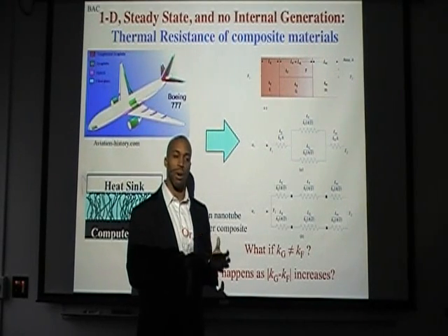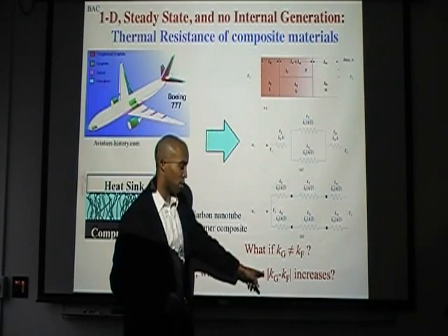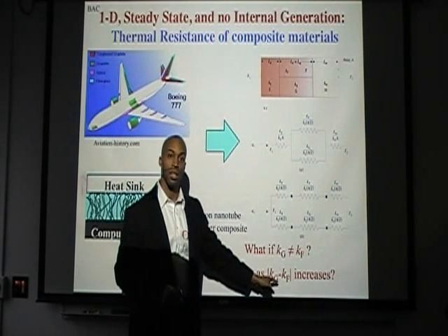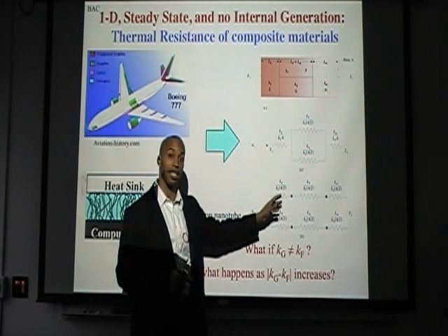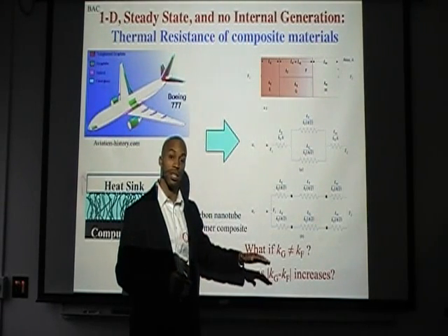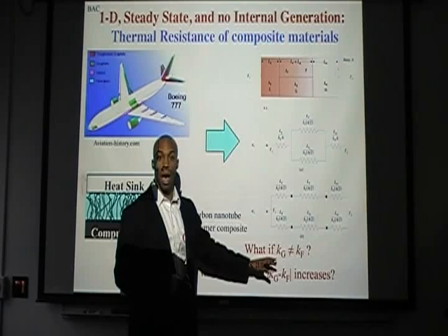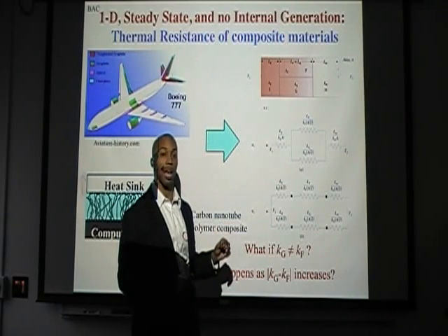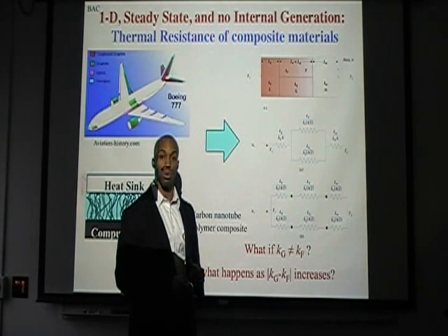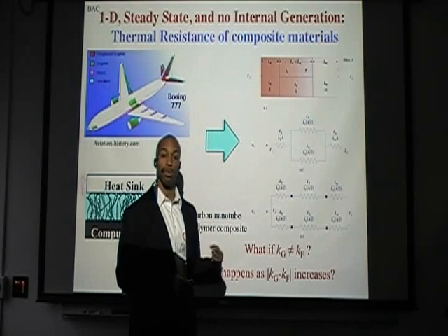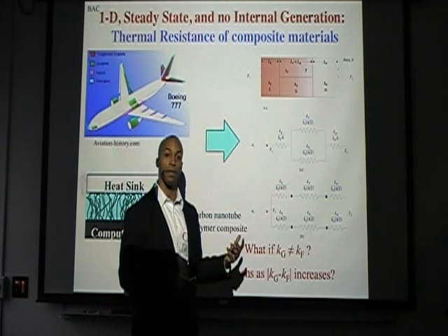But if you're out in practice making a design, you have to be aware that when this difference between thermal conductivities gets really large, the accuracy of your analysis will start to decrease. So it'll become less accurate. I might suggest, even if you had a problem like this in real life, you first work it using an equivalent circuit approach, but then use a more rigorous technique that handles two-dimensional heat transfer, and then compare the results just to see.